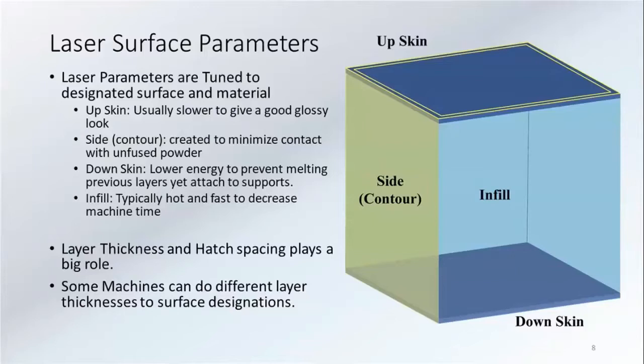If I do the contours and just raster those every other layer, it allows me to save a lot of that time. I still spend the 10 seconds for every recoat, but every other layer, instead of 5 minutes to weld, it's about 30 seconds. So there are different things you can do. The software that comes with the machines allows you to do different things, and some of that is patent-based, and some is just based on the programmers who developed everything.